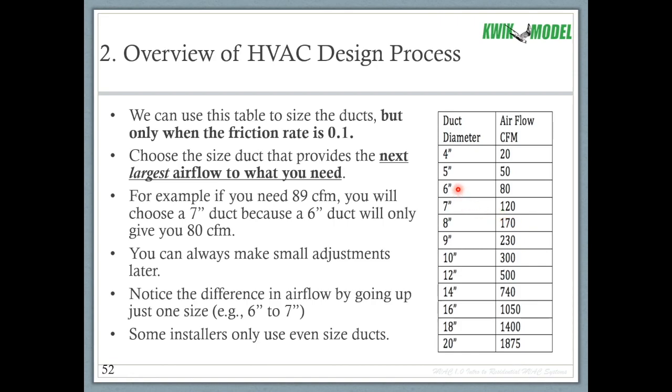I run into a lot of contractors who just don't use odd size ducts, and I say that's fine. If I call out a 7, round up to an 8. On the supply side, I've never ever had a problem with ducts being oversized. You get better airflow, your capacity goes up. There are some downsides to it. You get a little bit more surface area in a hot attic, so you might get a little bit more heat transfer, but overall it will work. In order for ducts to be too big, they have to be way too big. You have to need an 8-inch duct, but you put in a 14 or something like that. That's not going to happen typically.